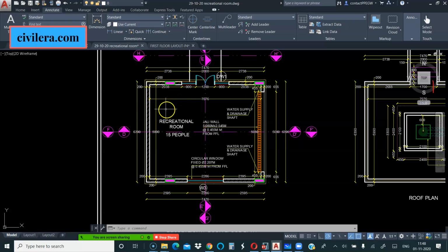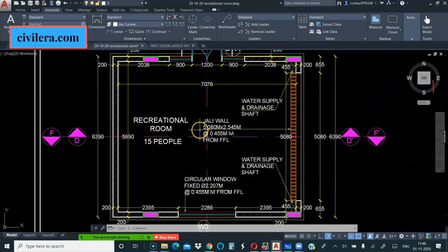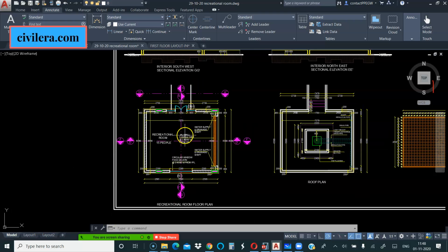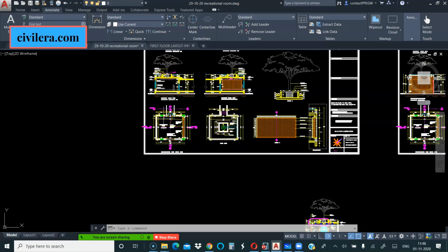If this is a big tree which is being brought and kept here, then I need to design the entire slab for that weight. But if it's a sapling he is planting here, then the chance of that being moved is very rare. It's not going to be moved. So I don't need to take that weight in the corridor at least. If it's a big tree being brought, then even in the corridor, everywhere, I will have to consider some kind of cushion. So all that is important.